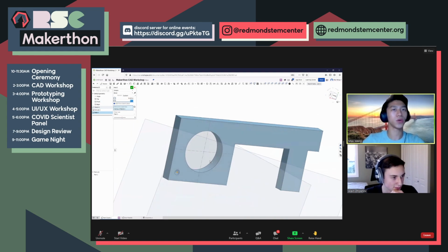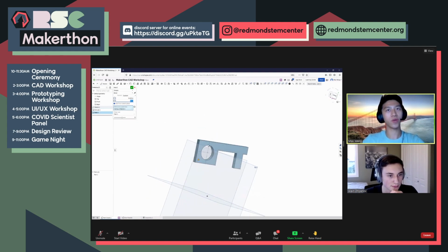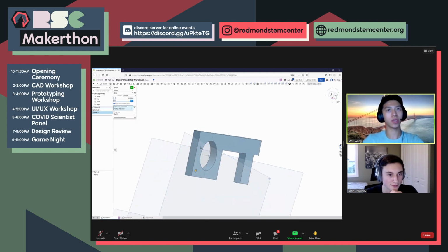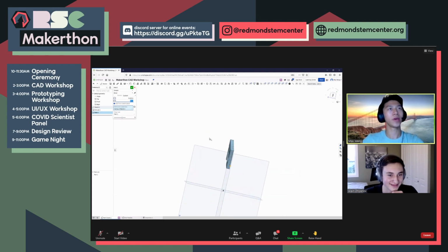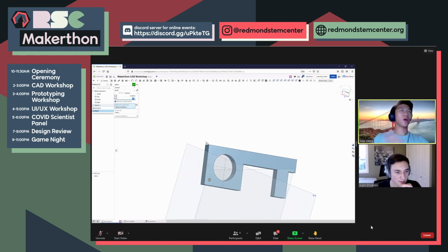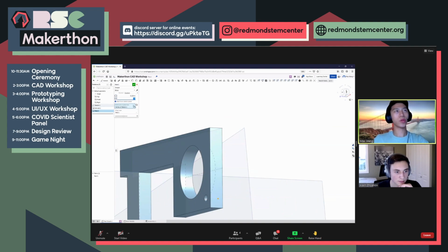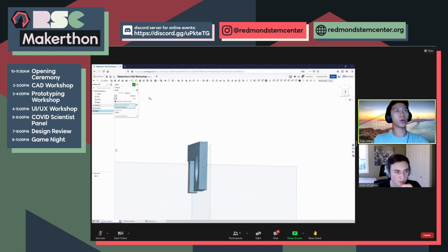And this is the depth of the hole. So imagine if this profile was extruded 30 inches instead of 0.25 inches like we just did. If it was 30 inches, it was way over there, then this hole would just barely go through the object. So this is the depth of the hole that is extruded. So 30 inches is the default. You can make it however long and short you want. I can make it 1 inch. It would still be the same because this is only a 1/4 inch, and 1 inch is greater than a 1/4 inch.